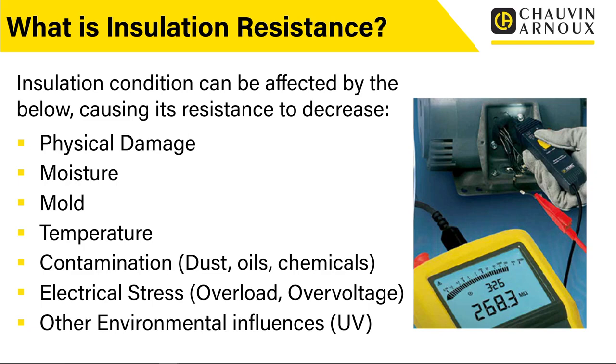There are other environmental factors that we need to consider, and a typical one that comes across quite a lot, particularly with PVC cables, is UV, ultraviolet. So if we're using PVC cables outside, they will be exposed to ultraviolet, and ultraviolet can degrade that insulation over time. It's very common to see, if you've got the grey twin and earth cables outside, where they've been exposed to UV, you will notice that they get a white sort of coating on there. It's almost bleached the surface, and in extreme conditions you'll see it goes quite hard and brittle and crusty and actually starts to break down over time.